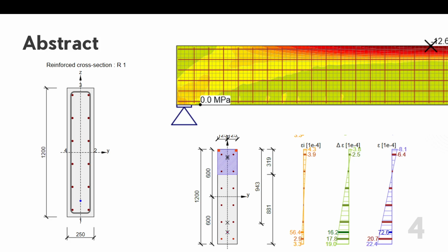The concrete between the cracks still carries tension, which is associated with the diagram of the reinforcement rebars. So you will see a different diagram, where tension stiffening is involved. We have the same physics but a different idealization. Keep this distinction in mind, and the results will make complete sense.